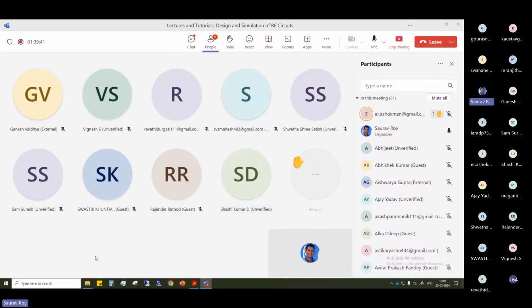Yeah, right. In that case, you obviously cannot use a simple circuit like that. You cannot just stack eight Wilkinson dividers like that. There are solutions where you have a 1 to 10 divider. There are dividers like the multi-port Wilkinson divider. You can look into that, and there is also the Gysel power divider, where you have only one input and it will give you 8 output ports or 10 output ports. You can look into that, the N-port divider. That theory is also there.